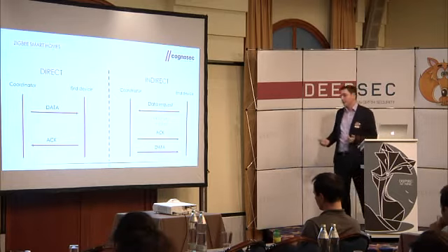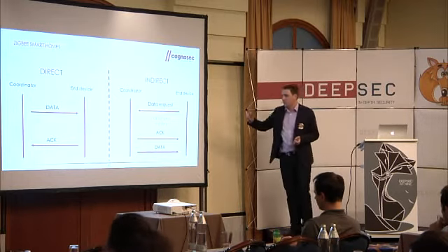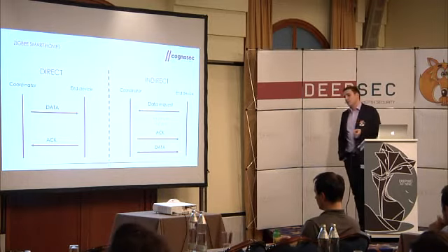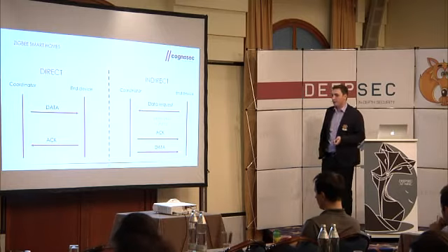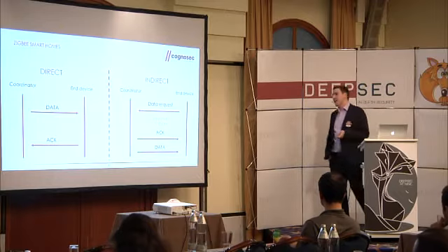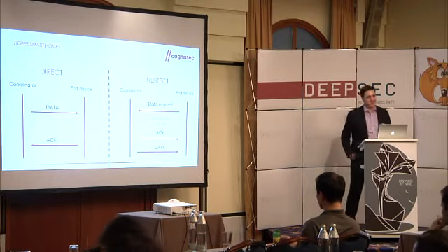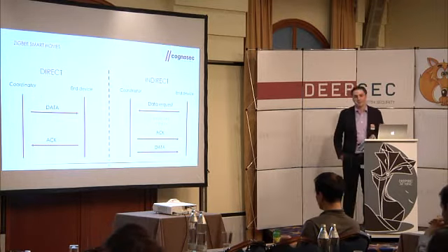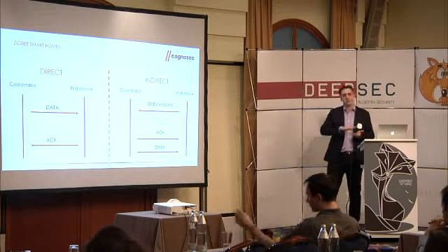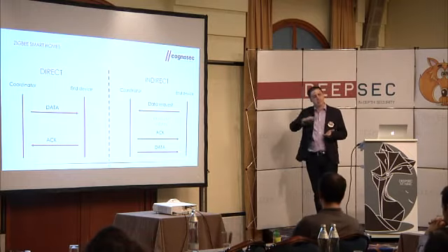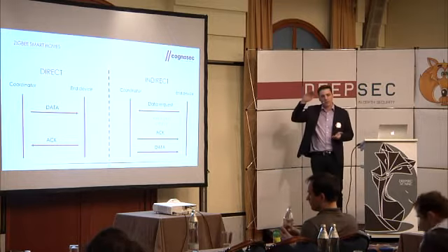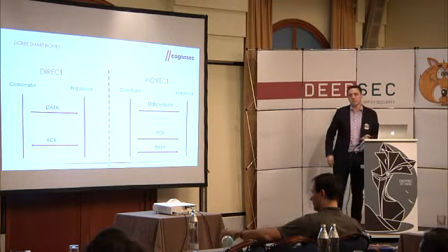And the problem is, it's a very small time frame. It's 0.8 milliseconds. You have to send the acknowledge, and since I am not the best programmer, it might be that my USRP implementation is too slow. It's 10 times too slow, because it goes from radio signal demodulation to C level, then to Python. I do some work on the packet, and then it goes again Python, C, and then it gets sent using the USRP.